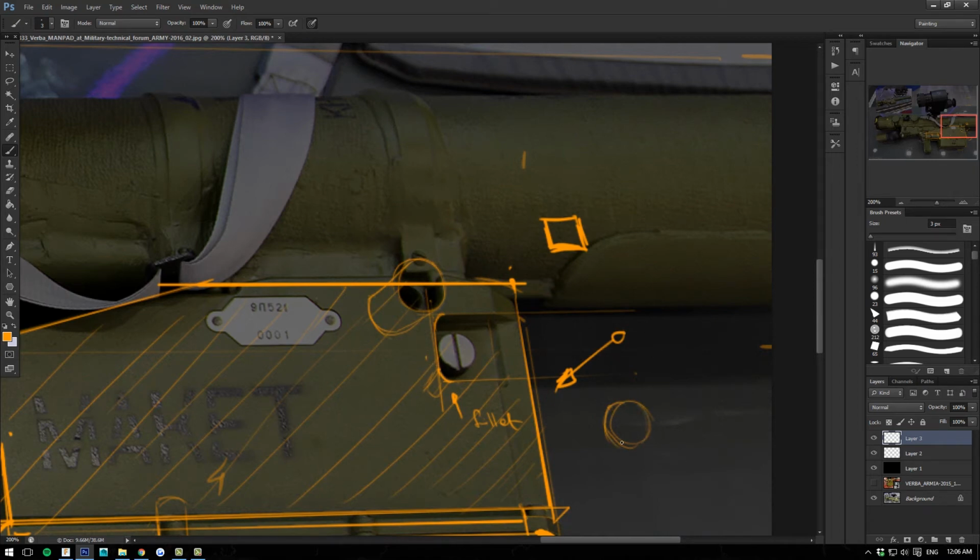So it's only going to be the head of the cylinder, and then we're going to use a coplanar face somewhere here just to look at this bolt from the side, and we're going to make this cut. So we're going to just use a cube that's going to be intersecting, and it will create that cut.